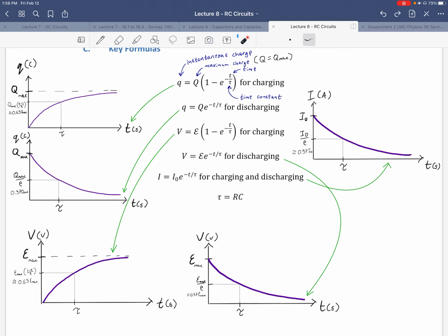It's just going down to 0. And that's because when we're charging up the capacitor and it's building up its opposing voltage to the battery, that's eventually slowing the circuit down in terms of the current flow until the circuit is at rest and there's no more current flow. On the other hand, when you're discharging a capacitor, well, that makes sense because once there's no charge left on the capacitor, there's nothing to flow downhill. So the current has decayed to 0 in that case too.